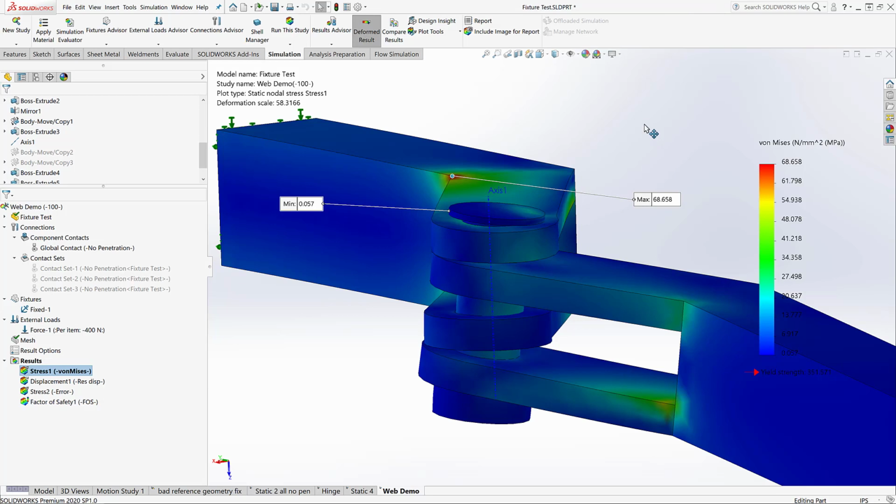It finished, and we didn't upset it too much. Our parts are still in our design space. That's great. Nothing flew out into empty space. And it looks like we did get a different answer than if we had bonded contacts. So specifying all the contacting faces and saying, hey, don't pass through itself, we did not actually get the same thing as a bonded contact.